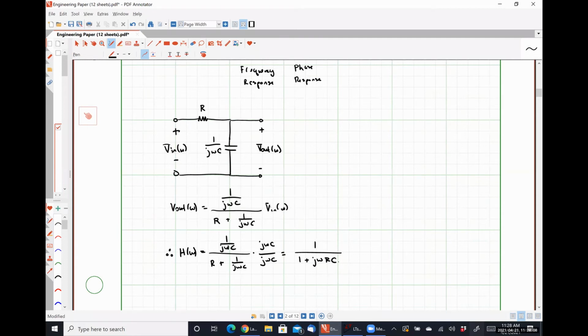We already know that it's a low pass filter, but we need to do some work to prove it. Because if we try to plot this function, we would run into some issues in as much as we have a complex number. So we're going to need to split this up into its frequency response and its phase response to get a total picture of how this filter behaves. So how could I get the magnitude of this? Square it and square root it.